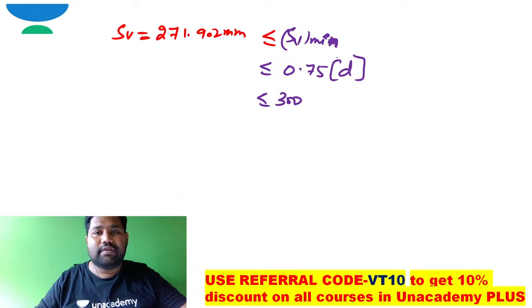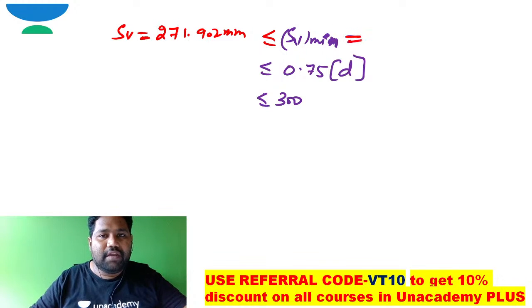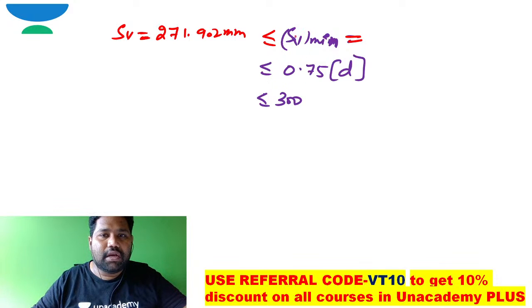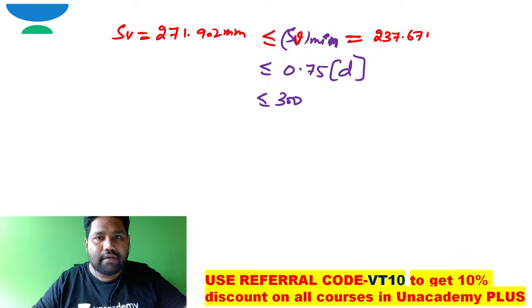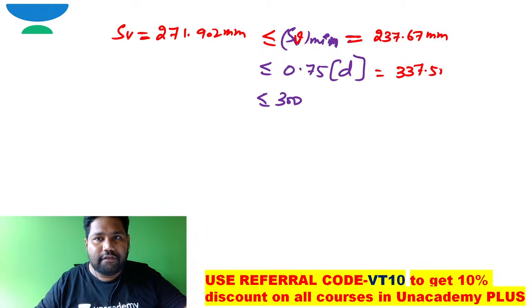So I can say SV minimum. What is the value of minimum shear reinforcement for the same problem? Maybe in your previous problems for the same statement, we got the minimum shear reinforcement spacing as 237.67 millimeter. This is 0.75 times of D. It is 0.75 times of D. Definitely, it will be 337.5 millimeter.